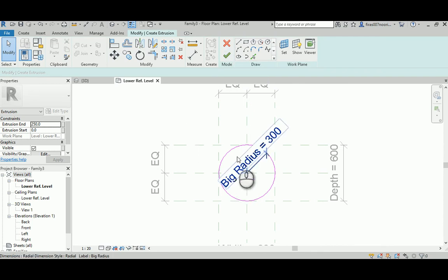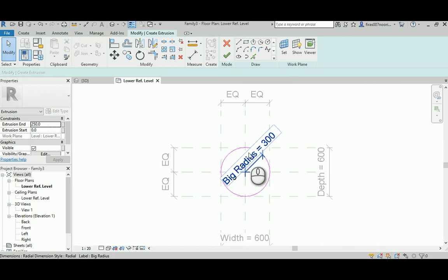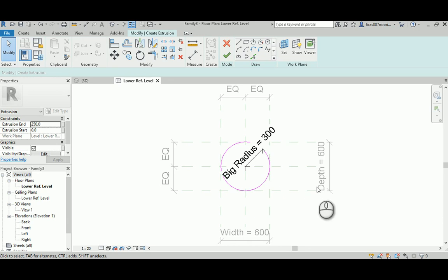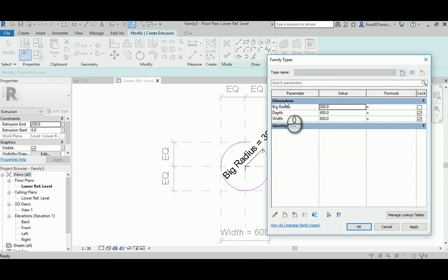and go ahead to make the height or the Z value of it, it's a really good idea to test and to link it actually to the depth and width that we have here. It's a pre-made parameter. That's the depth, and that's been predefined for us by the template of a Revit family column. So let's go here, and as you can see,